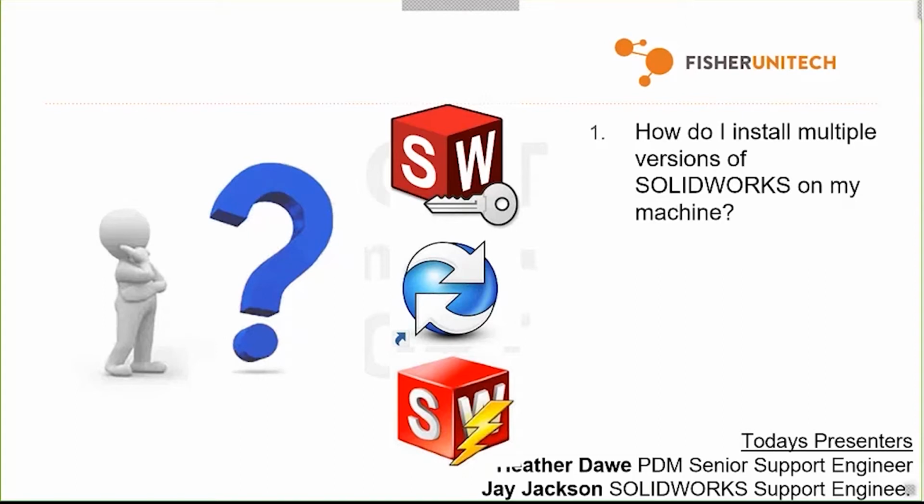Same goes with PDM. You can only have one version of the PDM server and client on machines. But that's okay because you can open 2016 files with SolidWorks PDM 2017 or 18 and save 2016 files into SolidWorks 2019. So you're not going to run into any issues there as far as the saving goes. It's just something to be aware of: when you upgrade to 19, if your server hasn't been upgraded, you want to make sure you keep your client on the same level. And I'm actually going to show you guys a little bit about that when I go to upgrade my 19 version since I haven't upgraded my PDM client.